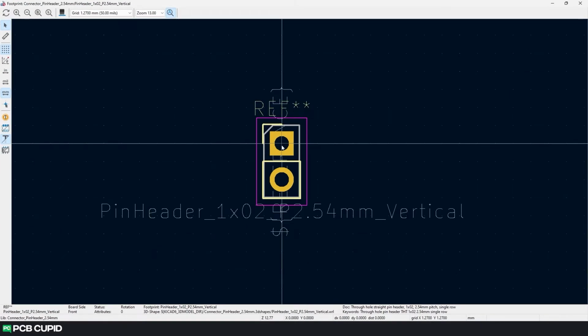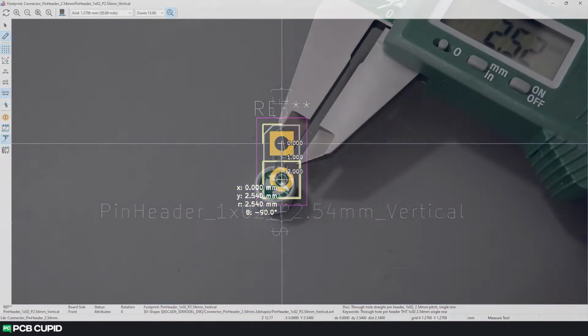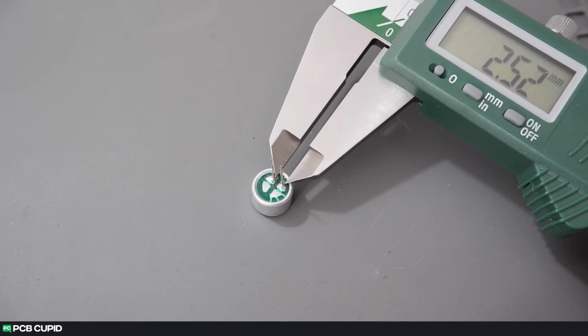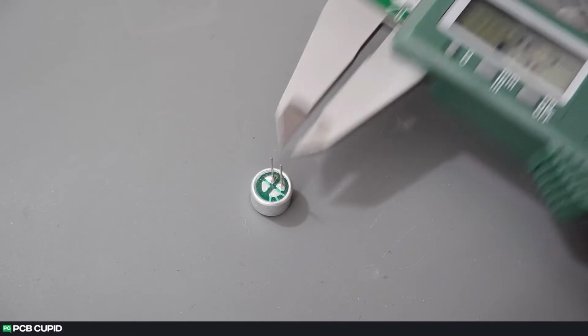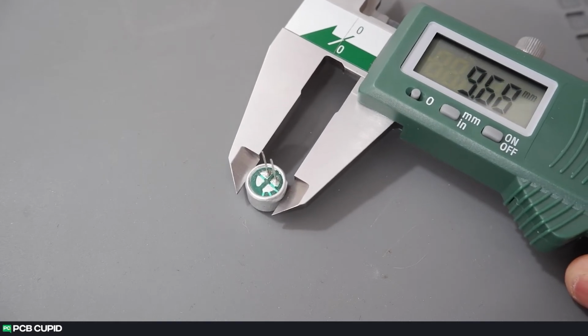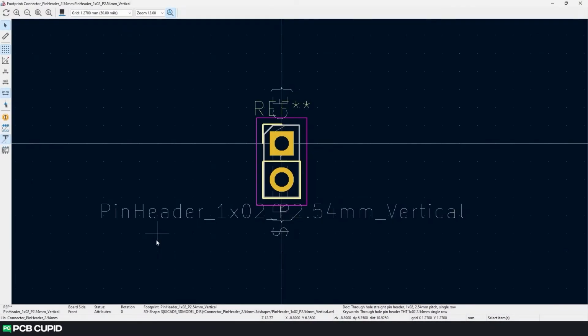After a few minutes of searching, I figured out this is the best alternative we have. So this has the same pitch distance between 2 pins similar to the condenser microphone that I have. But this might cause some issues with the other dimensions of the condenser microphone, for example, its diameter. But we can fix that while making the PCB layout.